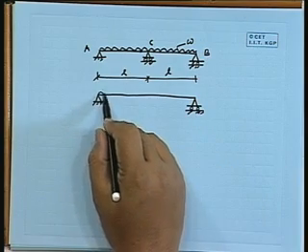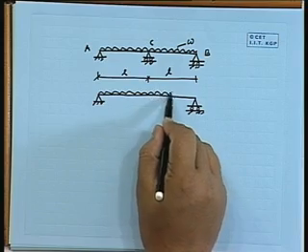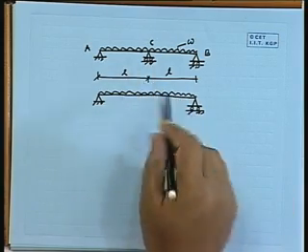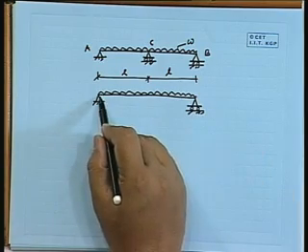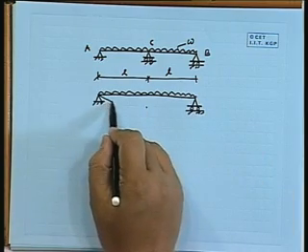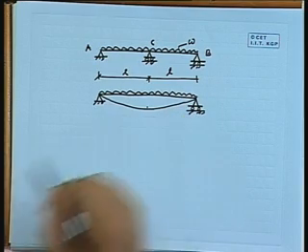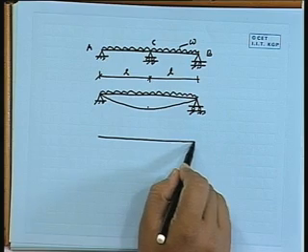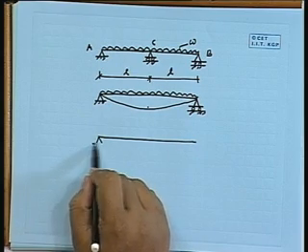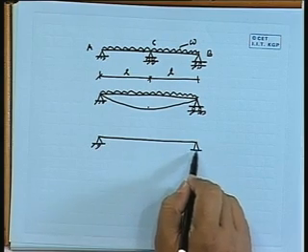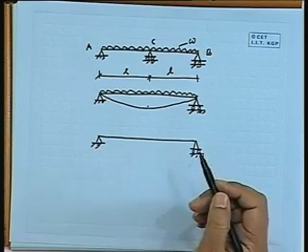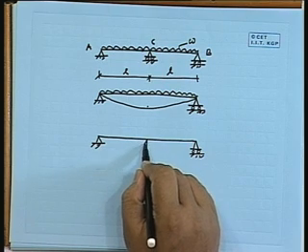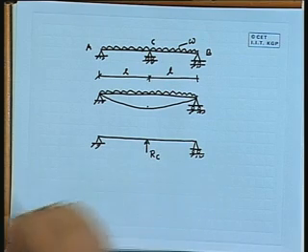Now, say at this level we remove the central support. Now, due to that we will get some deformation here. Now, we are not supposed to remove the support at the middle. To take care, we have to supply a reaction, say R_C.